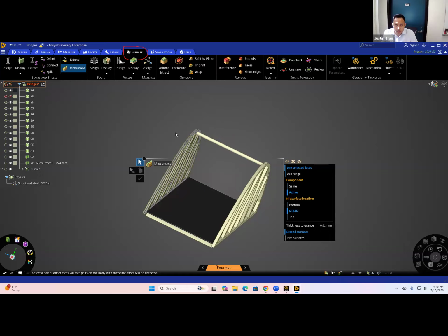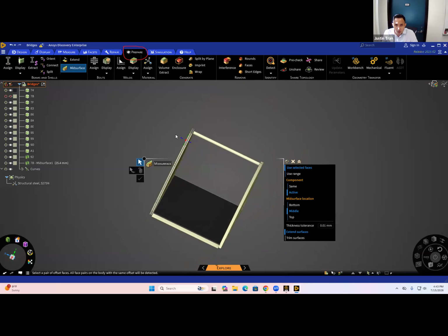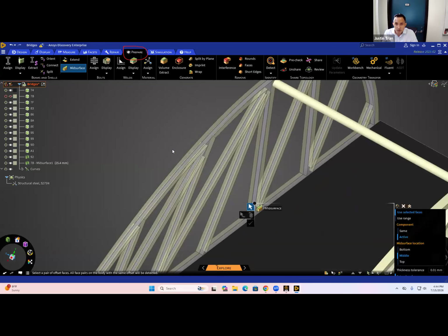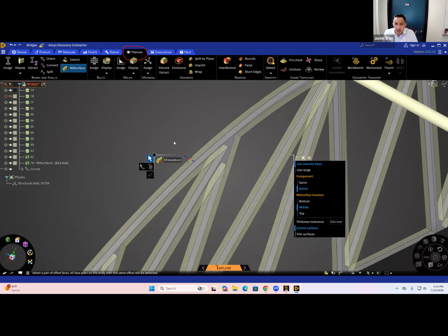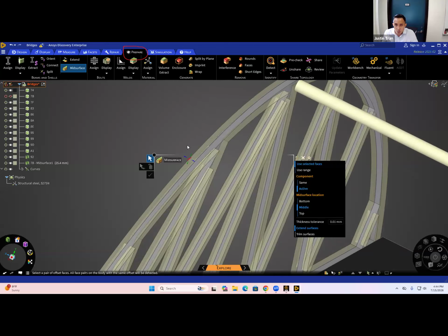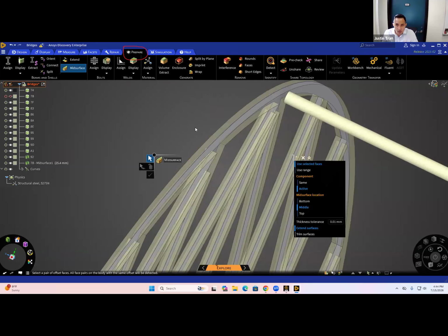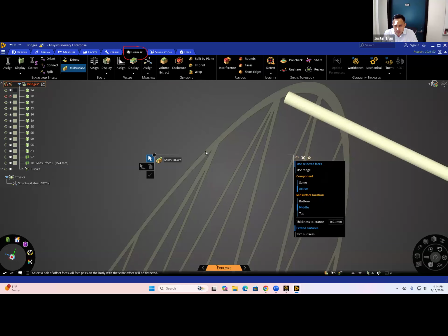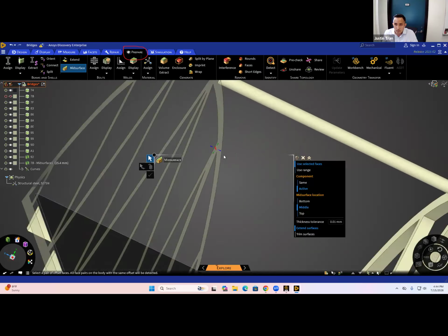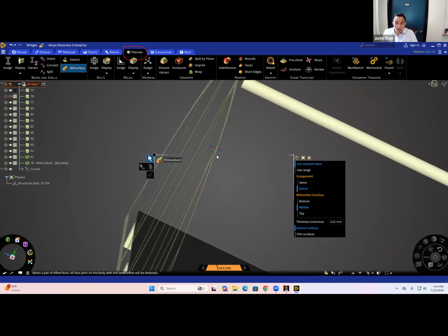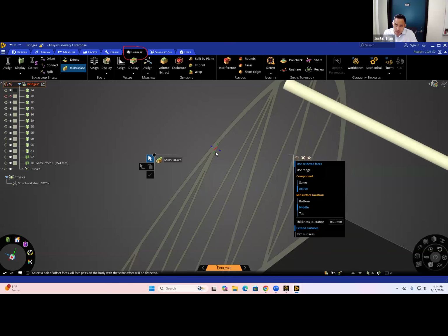After doing so, you can see that we've created our mid-surface. As long as you don't click, you can see the old surface that was there before. Zoom in and you can see the old surface grayed out, and in blue, the new mid-surface we just created, which is a shell of the previous one. Then you can left click once anywhere in the empty space and eliminate the old solid parts. That's our first mid-surface. Again, it's a very quick operation, but you have to make sure that you click on two parallel surfaces.